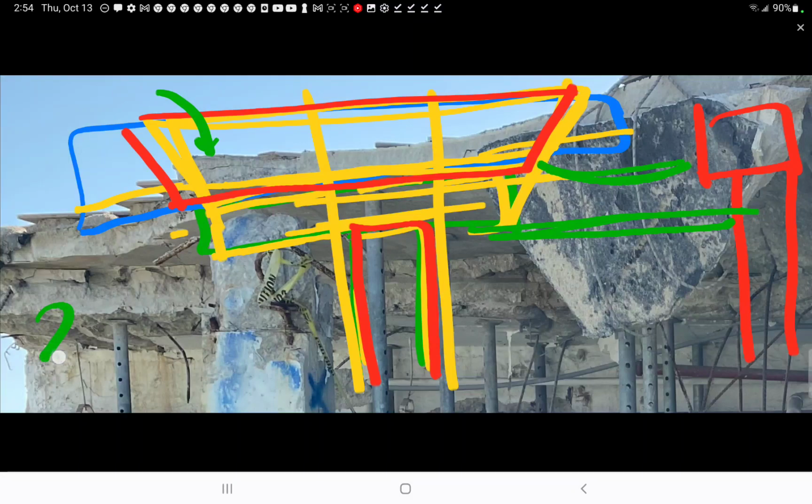Remember, in the previous video I said it's like having two 2x12s on top of each other, like scaffolding boards. Even if you don't screw them together, if you walk on one of them, you'll get a lot of deflection. You put another one right on top of the same one, and now you don't even have to screw them together. You can walk there, and it'll give you some deflection, but not enough where you're going to freak out and say, let's screw these boards together. No, just two 2x on scaffolding. No, it's not OSHA approved.